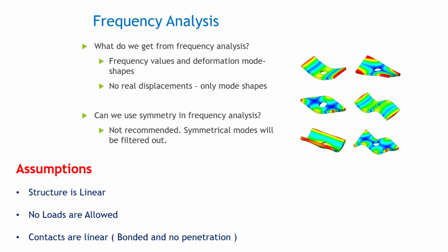What assumptions do we make for this? The first one is the structure is completely linear, and no loads like pressure or force are allowed in the modal analysis or frequency analysis. The contacts are linear, like bonded or no penetration. These only we consider. So these are the assumptions while dealing with this particular modal analysis.